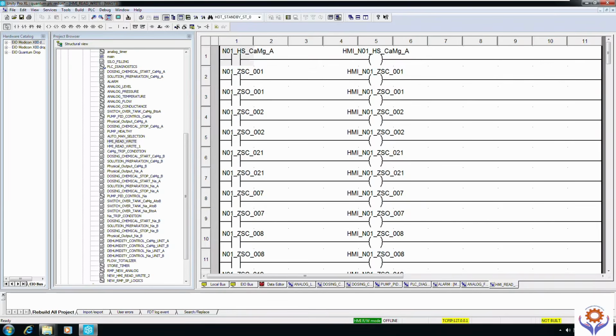You can use this even in the function block diagram, because the one which we showed now is ladder logic. If you need to use function block, you can use the move function block, and this directly will move one bit to bit. Also, if you need, you can utilize bit to word.